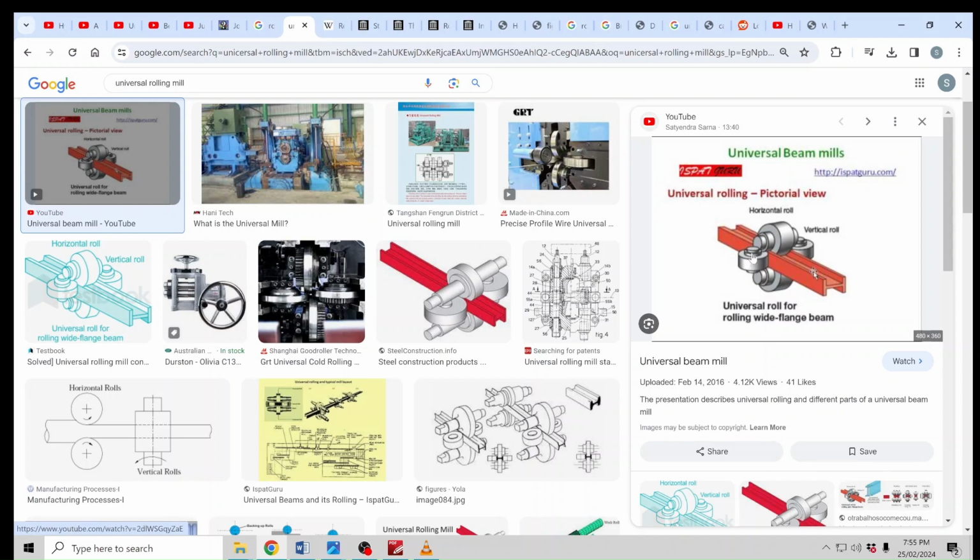And this was a design of John Arrowsmith and Rainer Dalen. They had rollers on the side in the vertical plane. And the advantage of this is that you could actually just move things in and out and change the shape of the steel that you want to roll. And this particular design doesn't have any grooves in it, but basically the gaps between the rollers is where the material is to pass through.